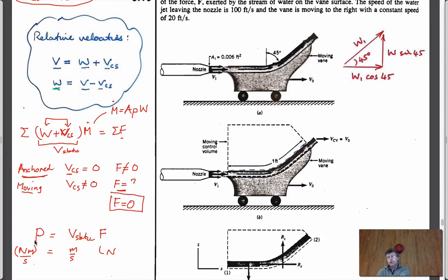Typically, you'll resolve them in one direction, but you need to be aware of the signs. If they're acting in, I mean, you have to, right? Otherwise, if these are just two scalar velocities and you add them together, they're always going to be positive. And so if you want this to equal 0, the cylinder's moving off this way, the relative to the cylinder velocity out of the cylinder is this way. So they're opposite to each other. So you have to, okay?